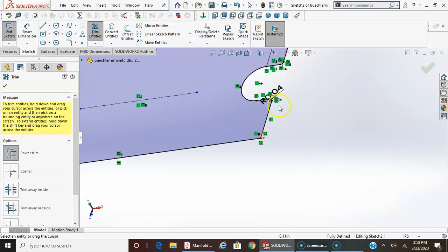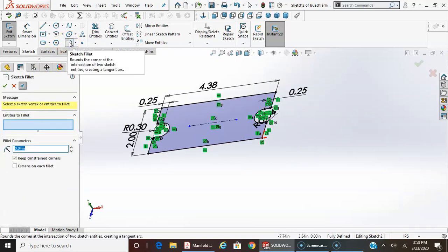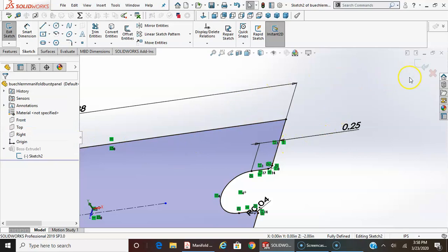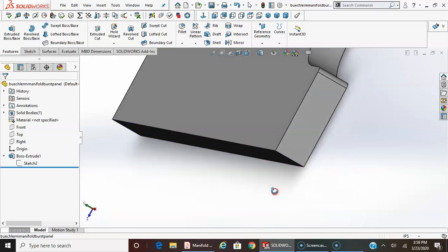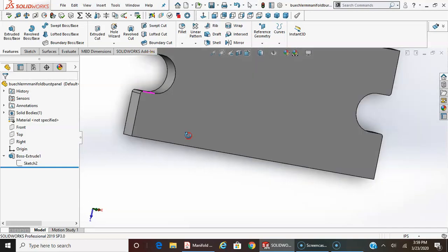I must have inadvertently selected it. When you do the sketch fillet, if you select a point, it can add it as a point. So sometimes we inadvertently add features in wrong dimensions. In that case, I was lucky to see that visually once I looked at my extrusion, and now it shows a sharp corner there. So just 4 fillets, 1, 2, 3, 4.